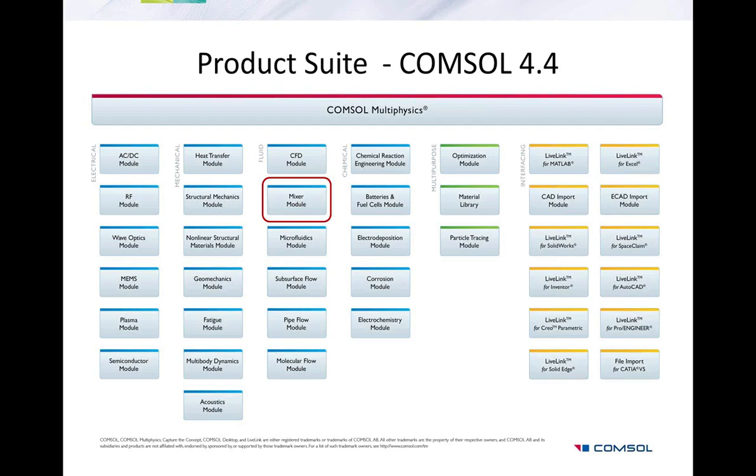Now at the top of the product suite, you can see the COMSOL Multiphysics base package. This is the engine for your modeling, including defining your own equations, meshing, solving, and post-processing. All of the modules contain user interfaces and predefined physics couplings for their specific application. For example, the CFD module contains physics interfaces for a variety of fluid modeling, like laminar, turbulent, and two-phase flow. And all the other physics interfaces in the other modules can be freely coupled to any of the others, such as the physics interfaces for solid mechanics coupled to a fluid flow interface in order to simulate fluid structure interaction.